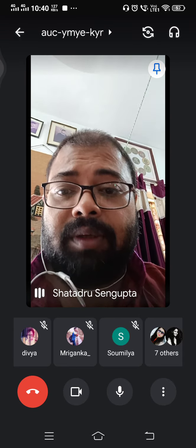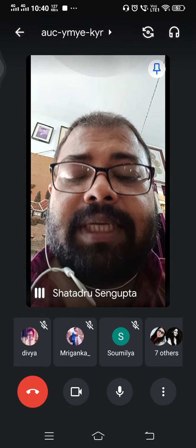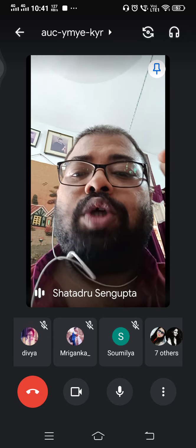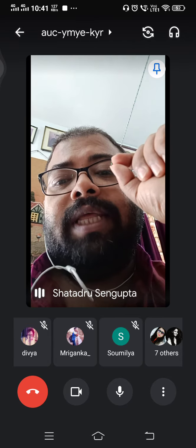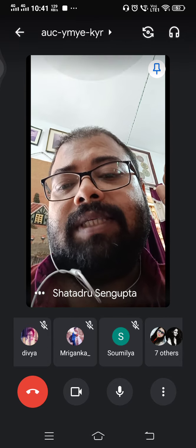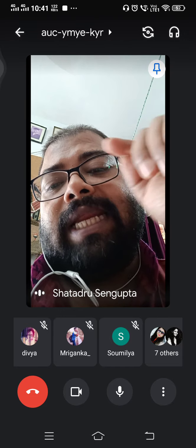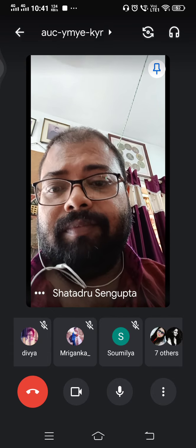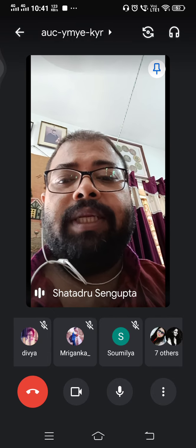Toggle switch, for example. Okay, once you press it, it's on. Once you press it, it's off. So it has to remember whether it was off or it was on. So there's a memory involved there as well. Somehow you have to store what state it was in the last time. So that is why you need a sequential circuit.